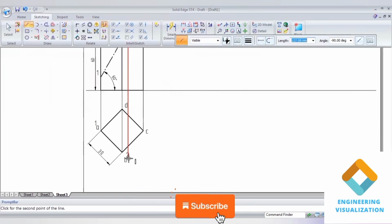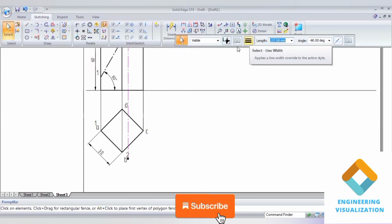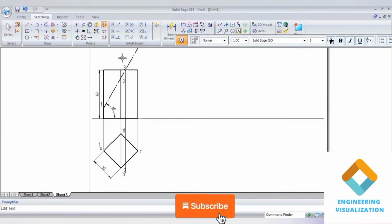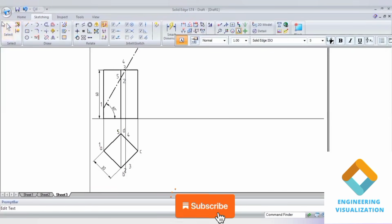That's why I'll be drawing a projection line from the intersection of these 2 points. By projecting it, you can see this is not falling on B, it is falling in between B and C. So that's why we have to draw another line here. I'll make that line a continuous line. So we can give that 3. And here, point number 4 is not falling on D, it is falling in between C and D. Then point 5 is falling exactly on the vertical edge D here. Now we are done with the namings.